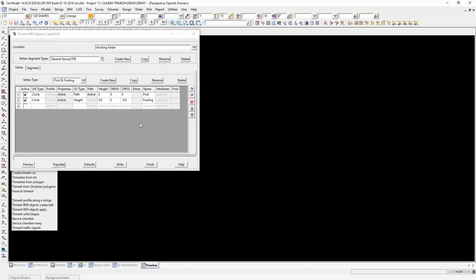So when you create or edit an option, we're looking to create it at the moment, then we'll go into the apply. So when they're used in 12D, a search is done for that file that I mentioned before in the usual suspects. So we're talking about the setups area, the user area, or the working folder. Now I have a file in different states in all three of those areas, so mine shows up with all three, but depends on what it finds. We're just going to work in our working folder.